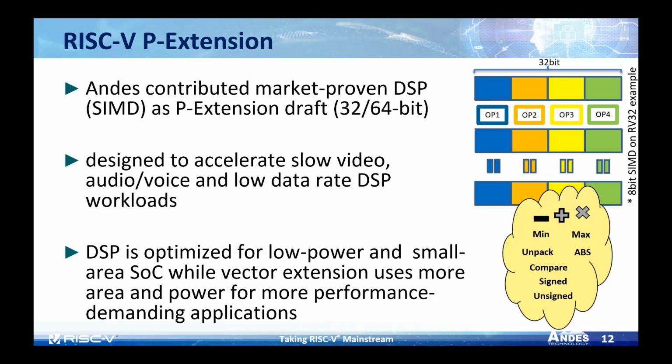The DSP extension, like I said, was developed by Andes. It was before in our proprietary devices and it was kind of closed source. But with RISC-V we have decided to open source it, make it available for the RISC-V community, so also our competitors can integrate it, and they will start hopefully soon. Interesting thing about this DSP is that you can use the standard general purpose registers, so you are not introducing new registers, therefore saving gate count in your final application.